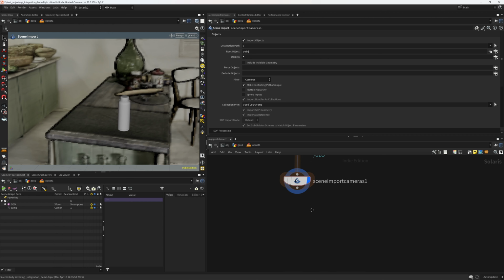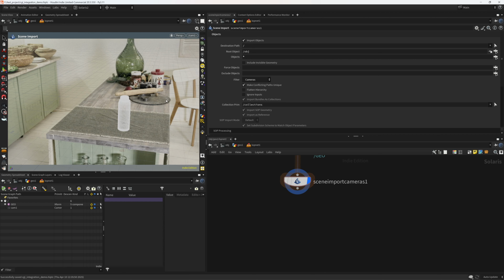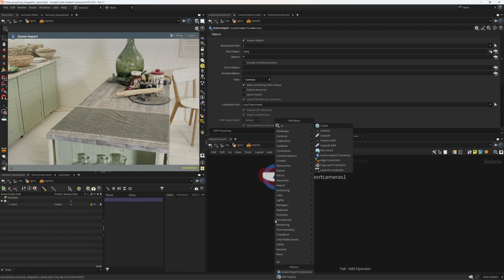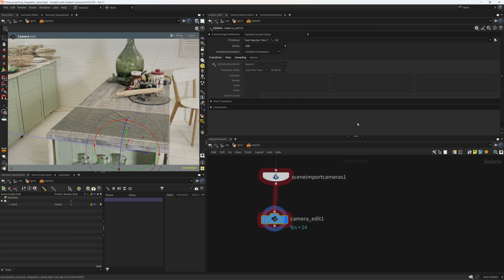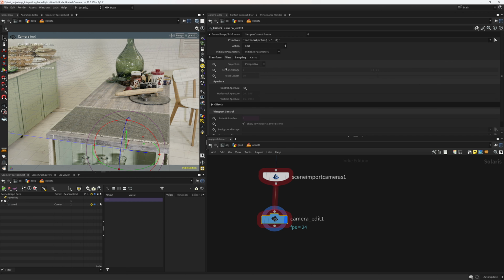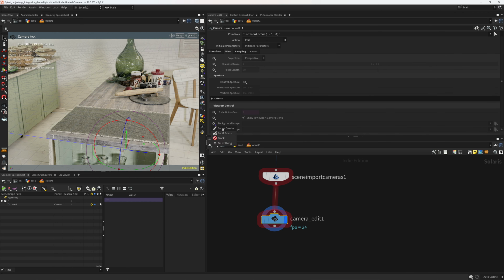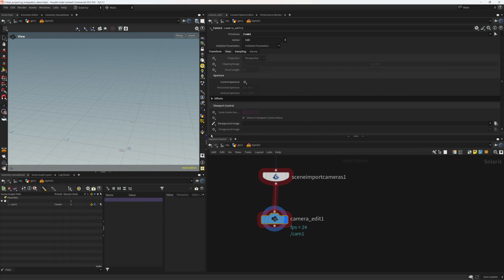Now we need to, let's see, if we remove the wireframe and we look through the solid view, or if we disable this and just look through the camera, we will have this background image. So I'm gonna instead do camera edit to remove the background. I believe this should work. So let's see, go into view and background image, set or create, and make sure I edit this camera. So that's fine. That removed the background. If we do nothing, this will load it back.